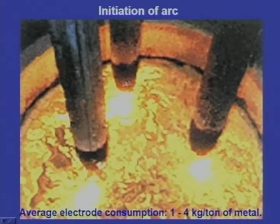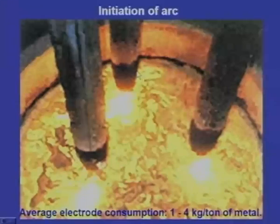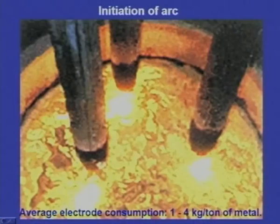The power is connected to these electrodes and the charge. The electrodes are struck against the charge and the arc is created. So this is the initiation of the arc, and because of this arc the graphite electrodes are consumed, and the average electrode consumption is 1 to 4 kg per ton of metal. So this is the consumption of the electrode.